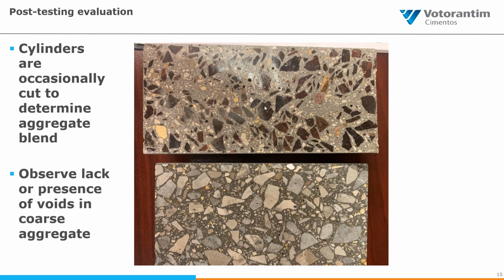that was generally from the use of a trap rock, which was used in this material. So early on in one of our first projects, we were unsure if we could consistently make that 48 to 52 GPa modulus of elasticity rating. So we initially started with a 50-50 blend of local limestone and trap rock from the northern peninsula of Michigan. We found eventually that the trap rock was very hard on the contractor's pump and on their pipes. So we eventually moved away from it as we moved up the building and saw that the limestone was sufficient, although the comfort level was less than what we initially would have liked.